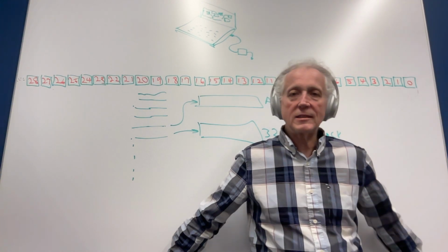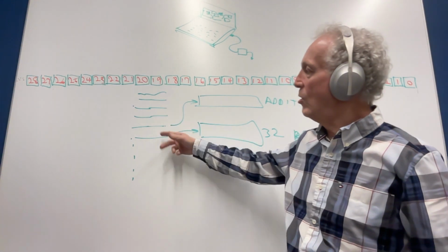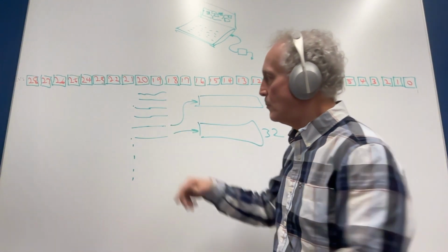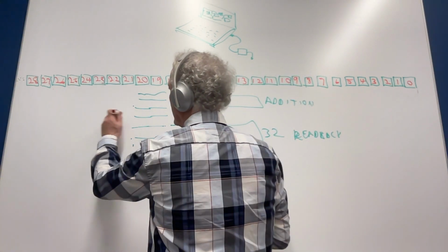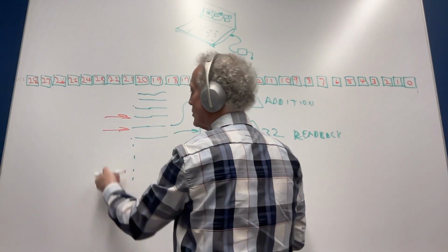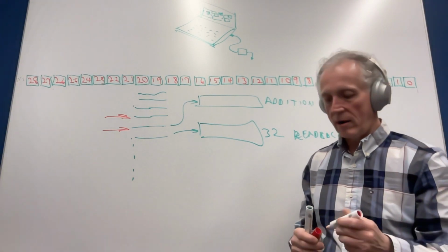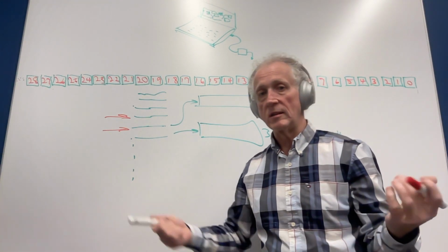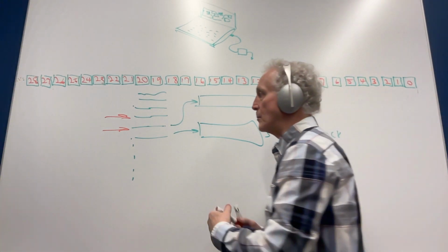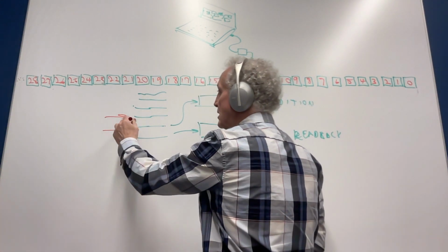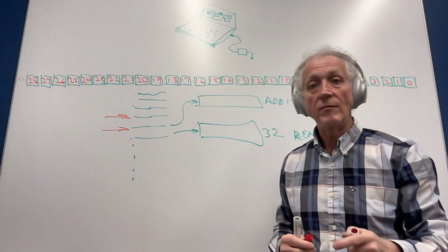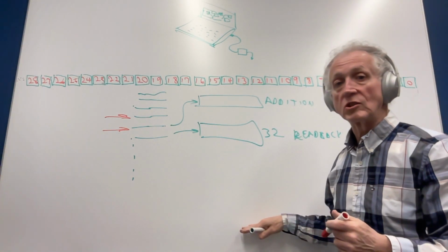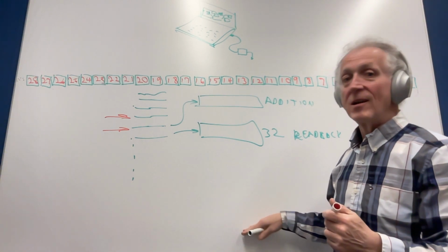You set up a capture register in hardware so that, because there's an instruction pointer for which instruction you are executing, and there are only 1024 instructions in a Sigma 100 core, at a particular instruction it'll take the contents of the 28-bit result and put it into a certain register, and then you can read that register out.